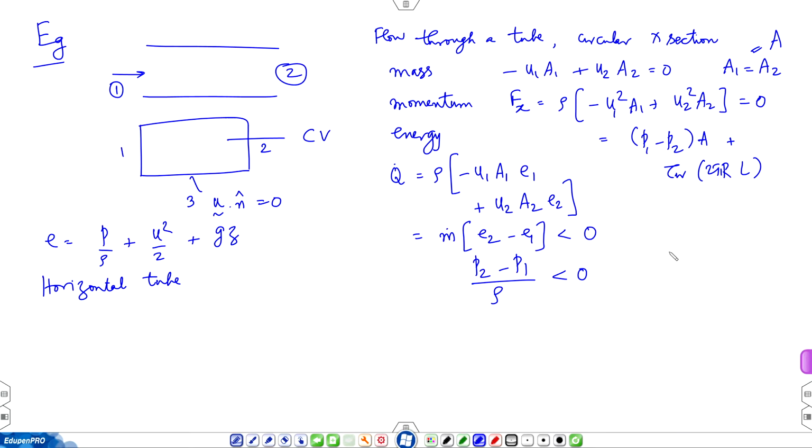In the previous class we had argued just based on the momentum equation that the wall is going to retard the flow, therefore the sign of tau wall should be negative, but now you are able to derive that based on the first and the second laws of thermodynamics, together we call the set the energy equation. So, P 2 minus P 1 is less than 0.